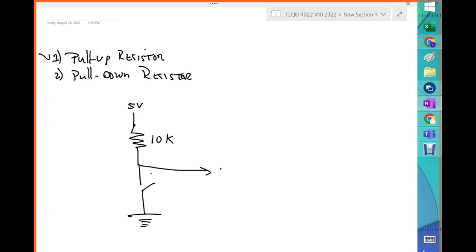In the pin mode, you have to declare the pins at this point. Pin 2 and pin 3 are, let's write that down here. Switch 1 will go to pin 2. Switch 2 will go to pin 3. And the output pin for the pump will be pin 4.